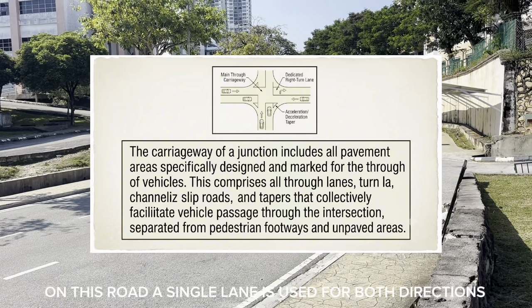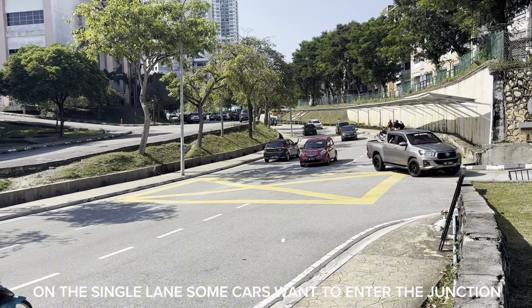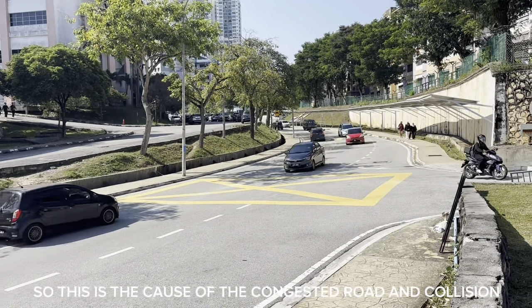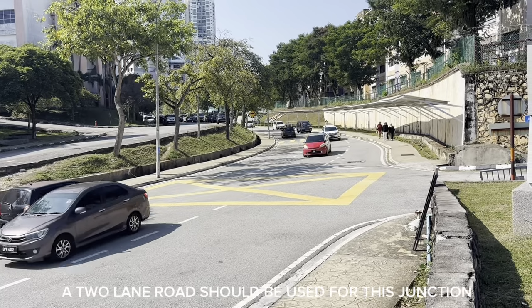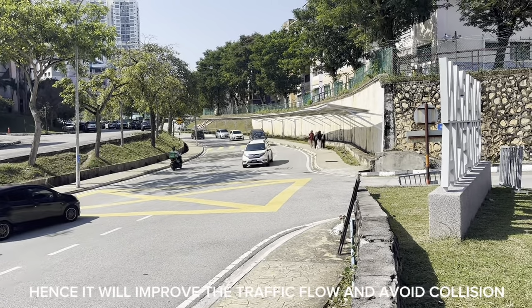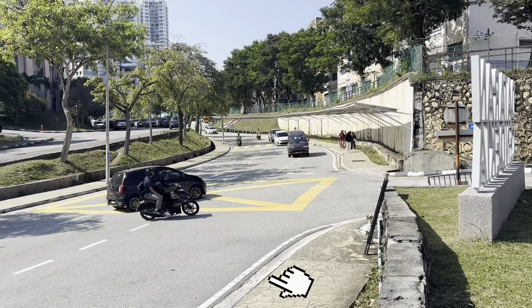On this road, a single lane is used for both directions. On this single lane, some cars want to enter the junction and some want to go straight. So this is the cause of the congested road and collision in this area. A two-lane road should be used for this junction, as the vehicles usually go straight and make turns. Hence, it will improve the traffic flow and avoid collision between the vehicles on the road.